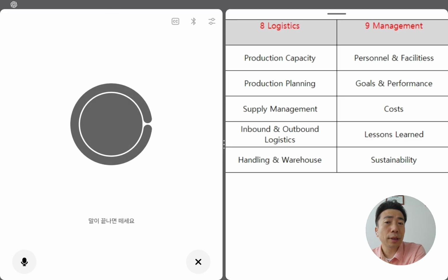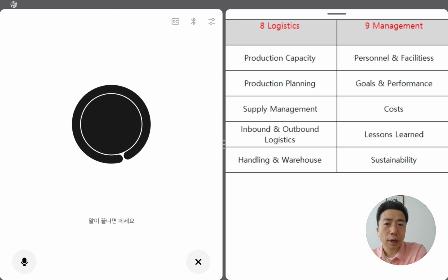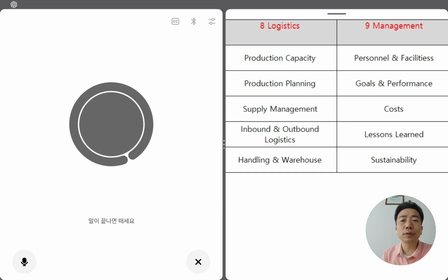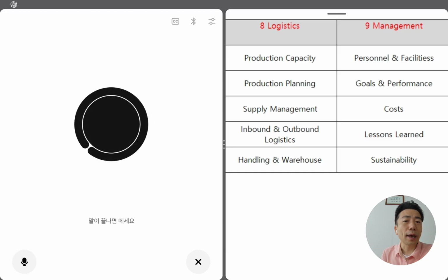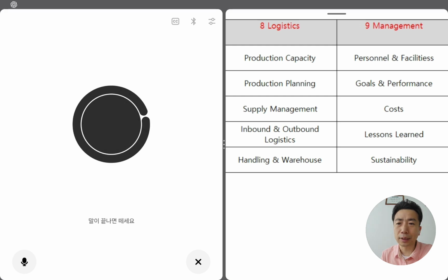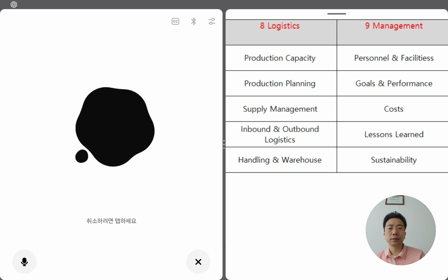Okay, I got it. So you mean as a quality manager, I just need to memorize the key message, like we have a system to manage MSD parts through sealed packaging, dry storage, floor life control, and baking if needed. Records are maintained as evidence. I think this short phrase would be really helpful for my real life situation.